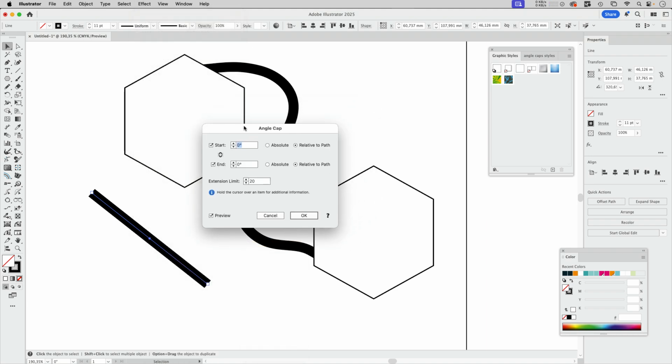And of course, when we do this for isometric drawings, then we set them to absolute, like this. So we could set them absolute, and we could have something like 30 and 60, but that is what we don't want. So what we can do is make it for the start point 30° absolute.